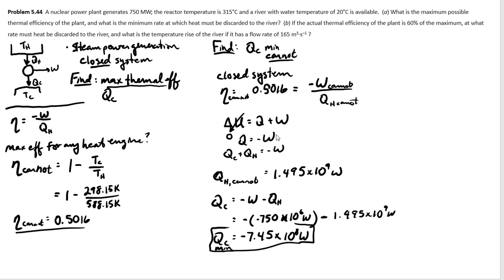For that efficient Carnot engine, we have the minimum amount of heat being absorbed and expelled to produce this amount of work. There are several ways you can think of it. We're getting the maximum amount of work from QH, expelling the minimum amount of QC, right? Or we're using the minimum amount of QH to generate the amount of work that this thermal cycle is producing.